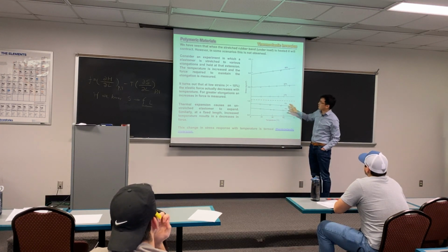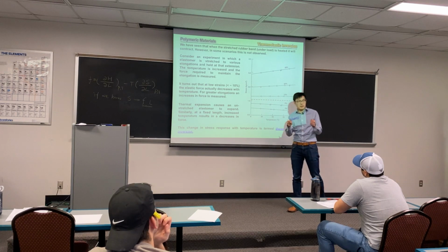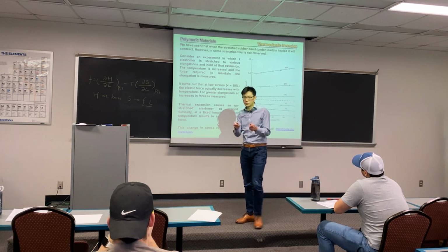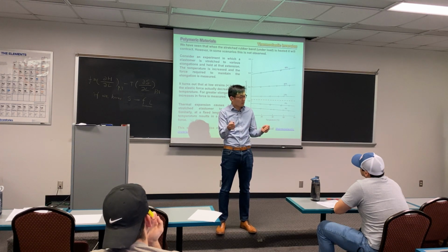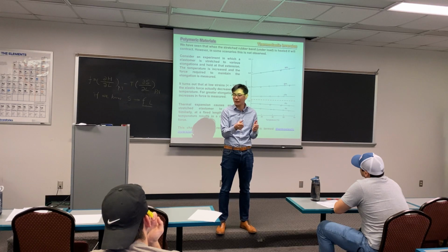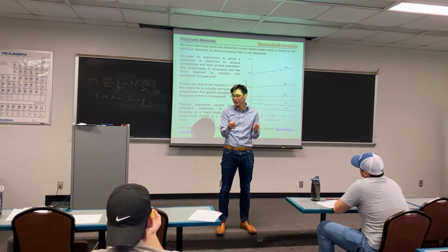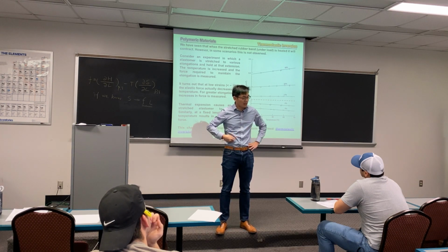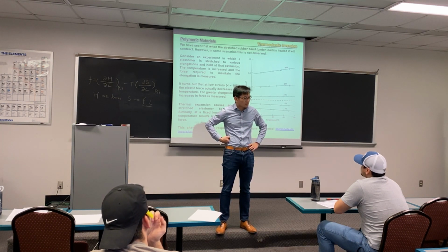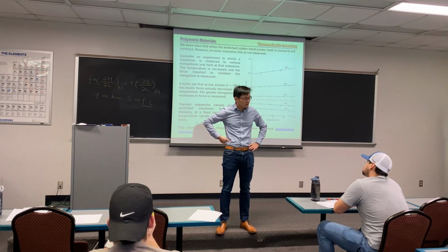So how do they perform this measurement? They pull a rubber band through an Instron. If you put a clamp on each side and pull the rubber band, you start to apply stress to the clamps on both sides. The more you pull, the larger the stress applied to your material.